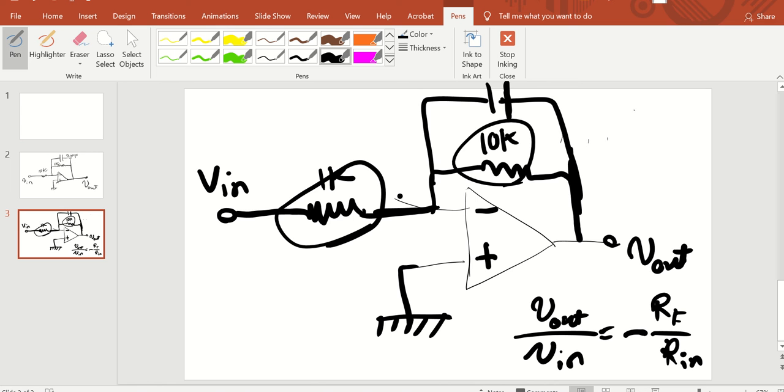If the frequency is high, it will act like a short. When it acts like a short, whatever you have at the output is equal to whatever you have at the input. For low frequency, when it charges up, then it holds basically voltage here, and this will always be true, right?